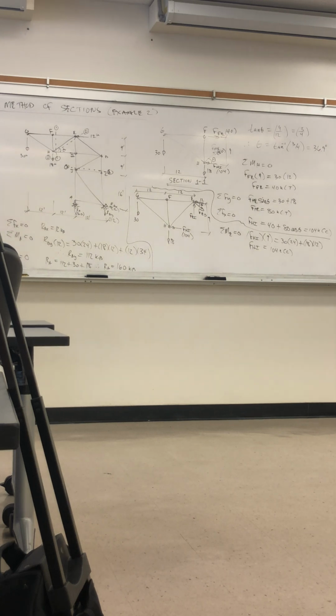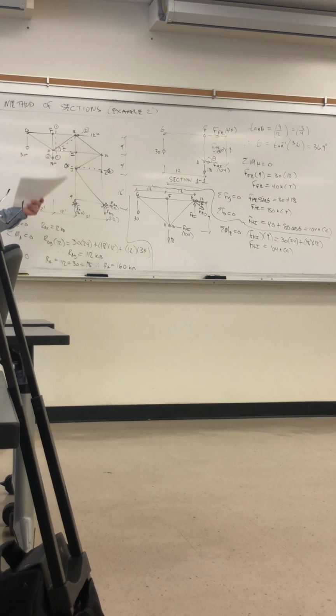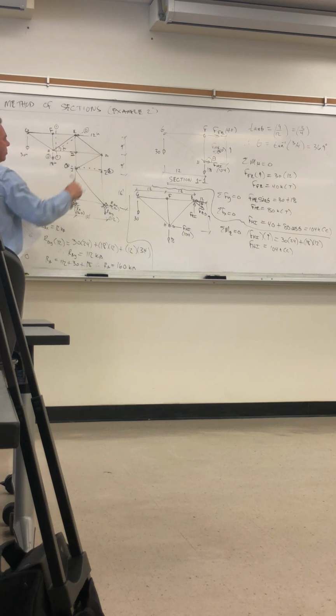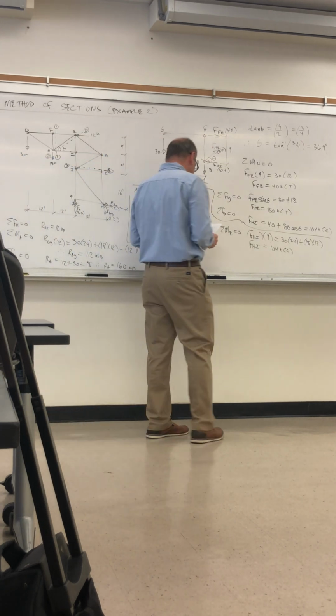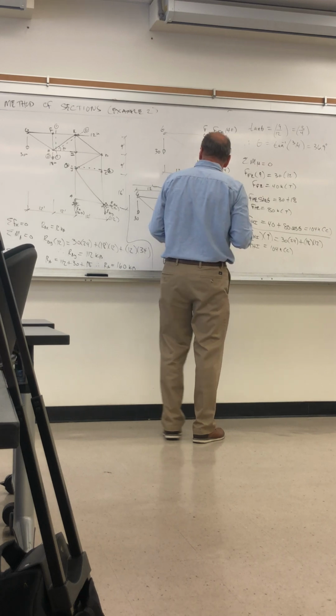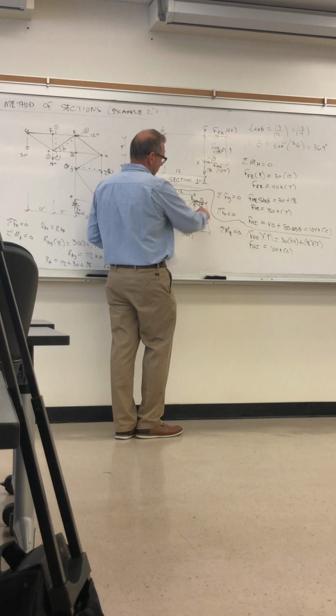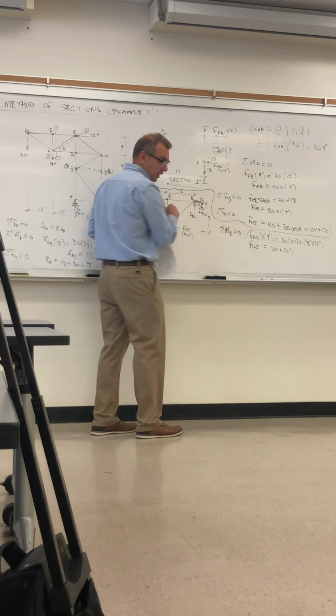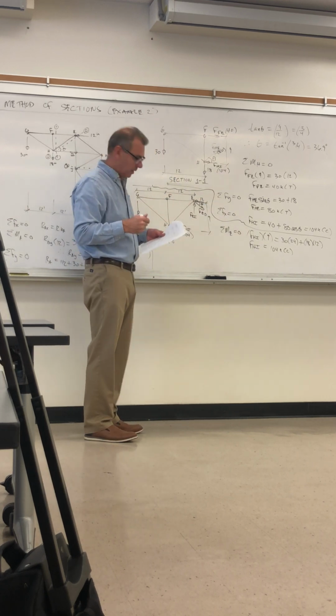Again, method of sections, notice how this section cut wasn't dependent on the prior section cut. It's not like the method of joints where we're going from one to one to one. We're just taking some example different section cuts, and we didn't need to start at this point and go from joint to joint to get there. That was summation of moments about E. Even this 12 kips, that applied force goes right into E, so that's not included in the summing of moments.